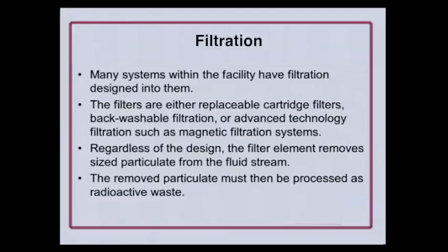It may be that it's backwashable, and by that it's designed so that you can basically wash. You take the filter out of service, but without opening up the system, you can do some valve lineups, and basically it washes all the collected residue off of the filter and disposes it down through hard piping to a rad waste system, and then it's processed with the rest of the liquid and solid rad waste.